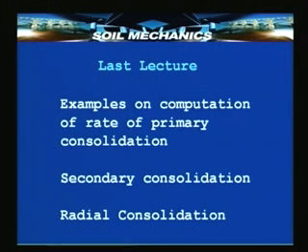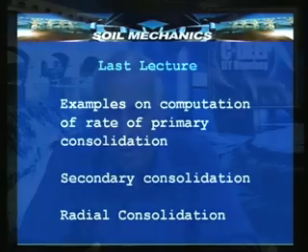The secondary consolidation is nothing but a consolidation which takes place in the form of plastic lag. That is, after the hydrodynamic lag which is arising due to slow flow of water is completed, the plastic flow of the particles and their readjustment starts. Load remaining same, this readjustment goes on for 2 days, 3 days at times, and that is the secondary consolidation part.